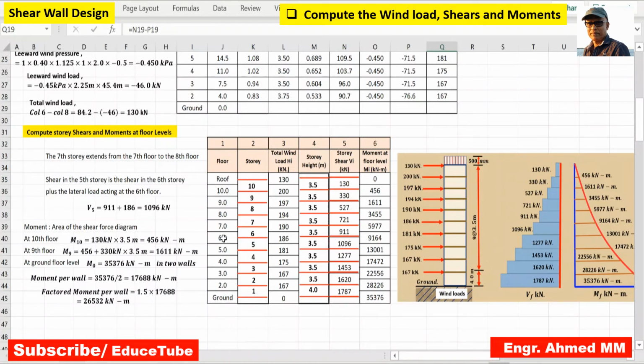You have to come here, 6th floor against 186 and 6th story. Shear in the 6th story is 911. So 911 plus 186, we get the shear in the 5th story. This way we have to calculate all the shears.